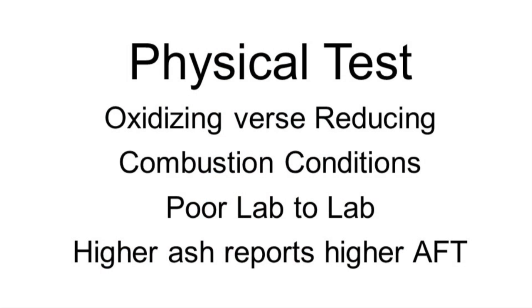One of the good things about the fusion test is that it is run in an oven, so we can therefore vary the atmosphere in the oven to look at both reducing and oxidizing conditions. We tend to get lower fusions in the reducing or poor combustion or maybe even low NOx firing that we might be doing. So I look for high CO as potentially causing some slags.